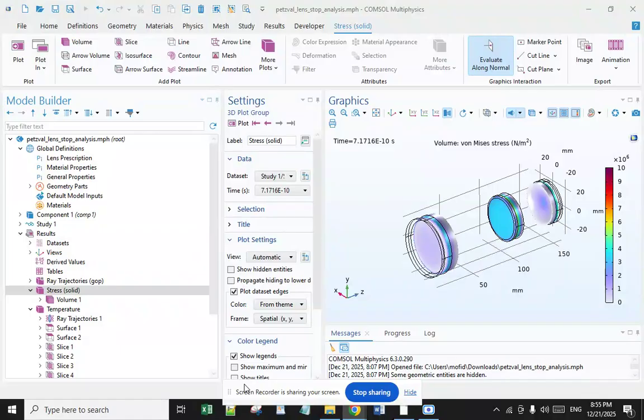Vacuum degassing. Vacuum degassing is a process of removing gases from compounds using vacuum, which become entrapped in the mixture when mixing the components. To assure a bubble-free mold when mixing resin and silicone rubbers and slower setting harder resins, a vacuum chamber is required. A small vacuum chamber is needed for de-airing, eliminating air bubbles from materials prior to their setting. The process is fairly straightforward. The casting or molding material is mixed according to the manufacturer's directions.